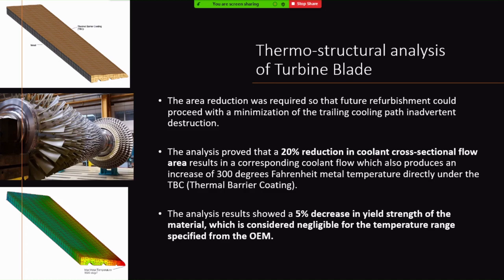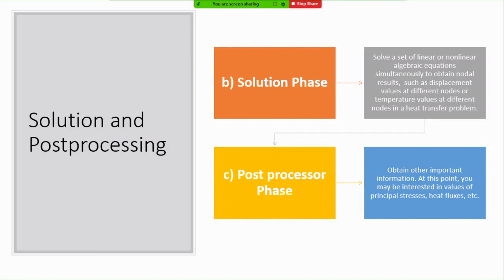Basically, the steps are to first create a model, mesh it, apply the load, then define the boundary conditions, then define the element properties, then assemble all the stiffness matrices, solve it, then calculate the stresses and deflections and so on. These are the steps through which it works: pre-processing phase, solution phase, post-processing phase. So at the back end, how it works, that is the most important.